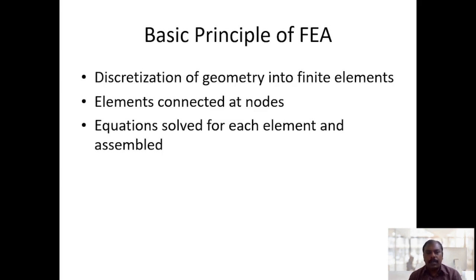Basic principle of FEA: discretization of geometry into finite elements. We are dividing the total continuum into small elements which have a finite length, and that process is called discretization. One element and another element are interconnected with nodes. So each and every element is connected with nodes. The equations are solved for each element and assembled. Every individual element is considered, the displacement of the nodes is solved for every element, and the displacements of all the elements are assembled to find out the results.